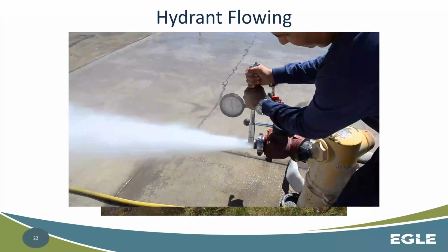So specifically what he's got going here, it's a little hard to see from this picture because the arm's in the way, but this actually is a Y apparatus. On this side of the Y, you can see it right here under his hand, it's a static pressure gauge. So as this hydrant is open, that static pressure gauge is giving a constant read of the pressure that's entering, and then they're allowing themselves off of this side to actually get flow from the hydrant.